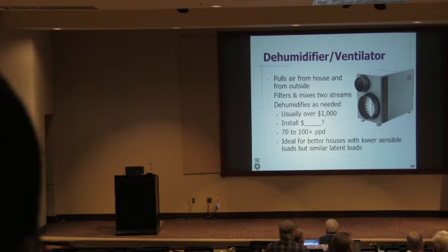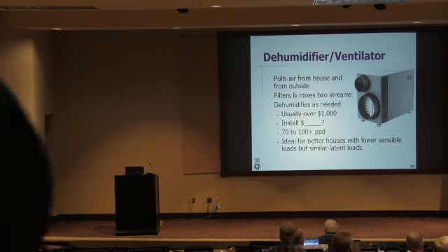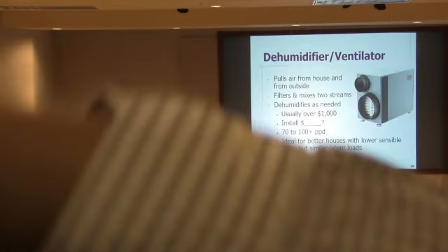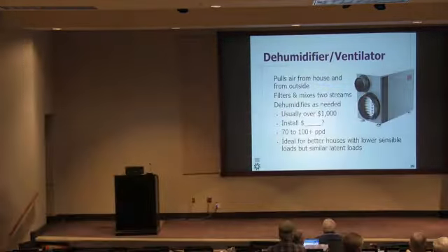So, that's an anecdotal, you could have a bad return or problem causing that type of stuff, but those humidifiers, we really shouldn't be having a need to humidify the air in our home. If you have that, lots of times it's because you're getting too much really cold outside air in the heating season that's making that air in the house super dry, and you're treating the symptom of leaky ducts by trying to add humidification back into the system.